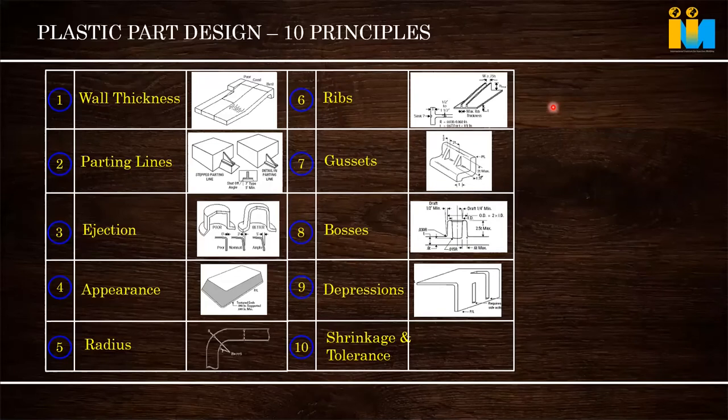Or every good product design company has their own studies, because it depends on their product, not only just the raw material, and how much detailing you are giving. Then radius, we have been discussing. Every sharp corner should be blended as much as possible. Otherwise, stress concentration happens at the corners or sharp edges and they start cracking.